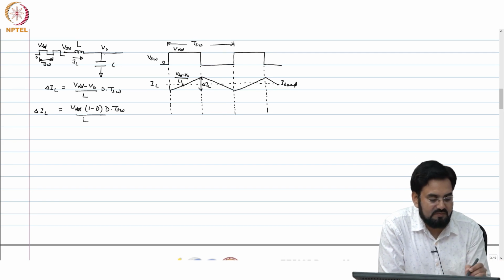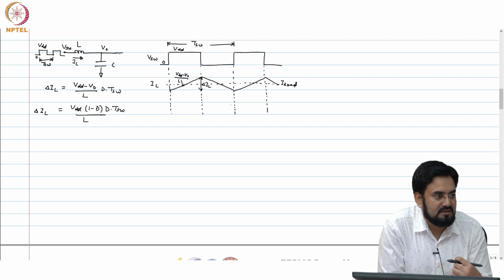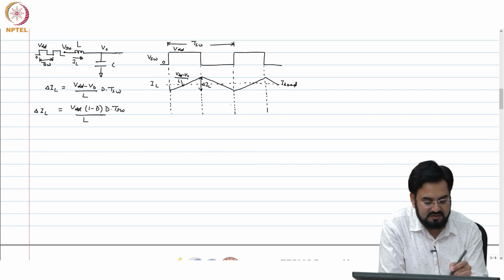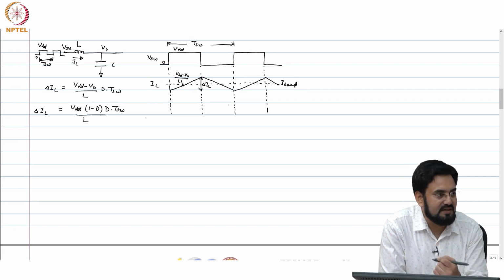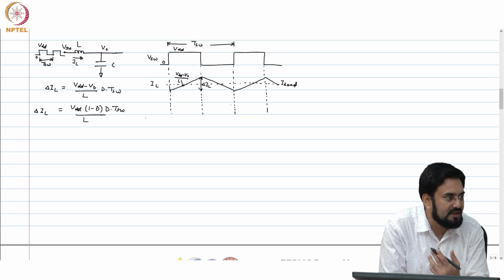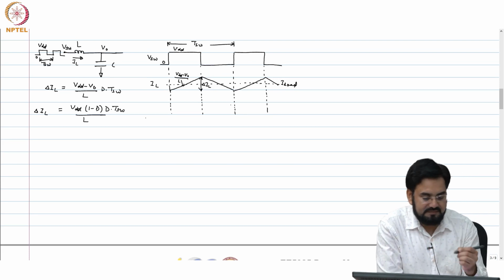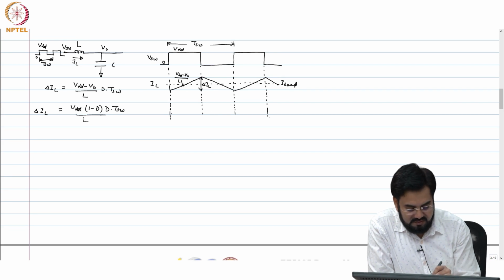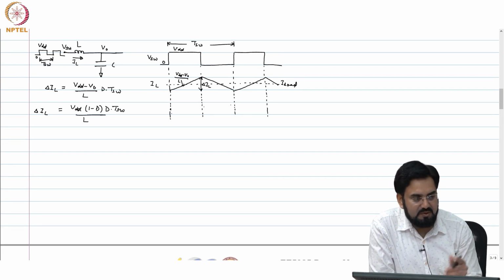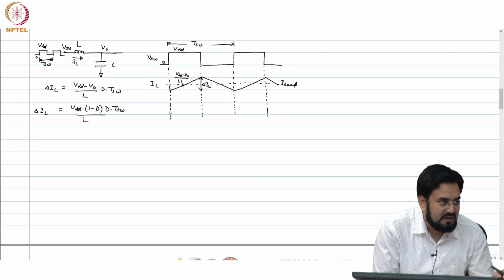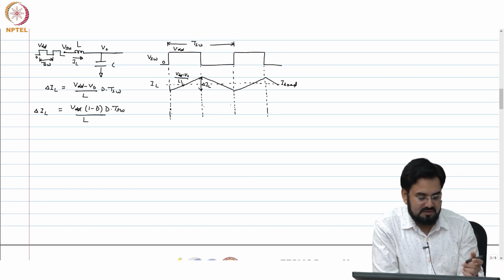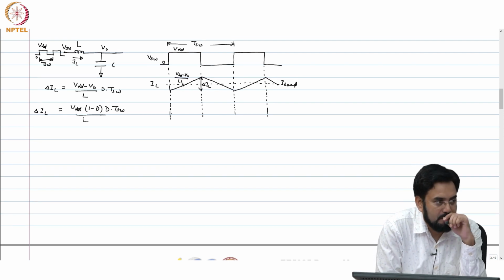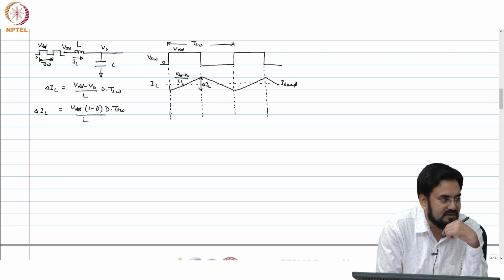Now, what is the equation for capacitor? I equal to C dV by dt. So, which means V is the integral of current. Now, this current will again get integrated and converted into voltage. So, you should have a parabolic kind of function, okay. Which means it will look more like a quasi sine kind of thing, because you have a parabola. So, where will the peak and valley of that parabola or sinusoid looking waveform be?